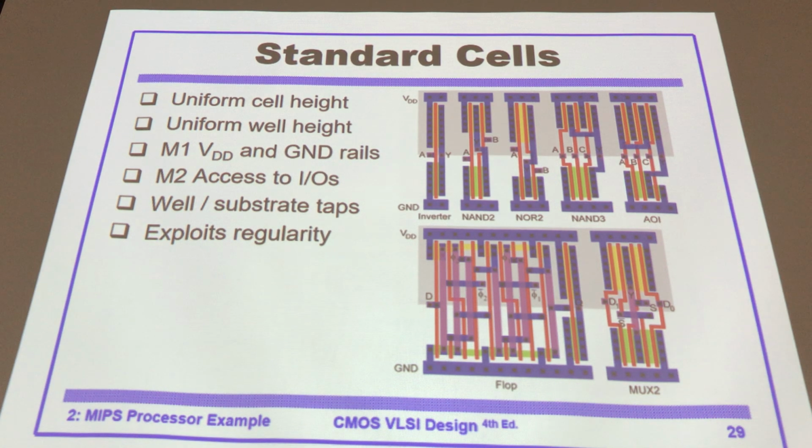Here we have two levels for the metal. Metal 1 for VDD and ground, and that's in blue. Okay, blue is metal 1, for power. And metal 2 for the I/O, the input signal A and output signal Y, using the second layer for the metal.